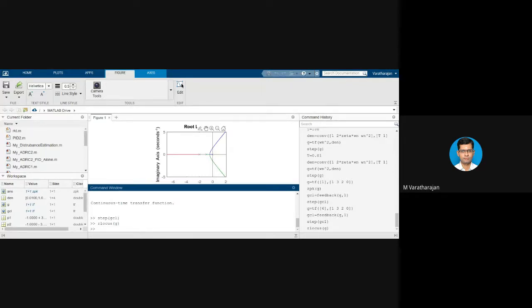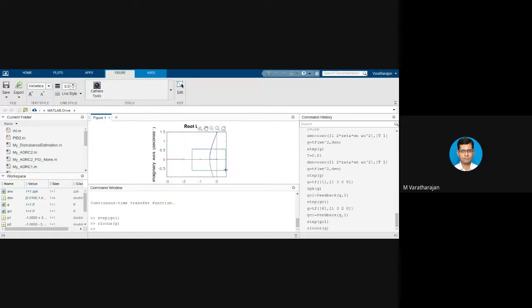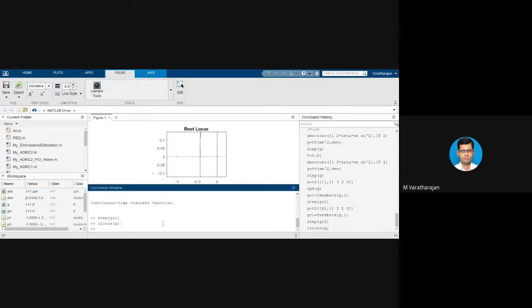Now, what happens is you can infer this behavior, that is, your closed loop pole positions, from the root locus. So what it says is at very low values of k, the X symbol indicates the closed loop pole. They will be on the right hand side. Whatever pole is on the right hand side will move towards the left, and whatever pole at -1 will move towards the right hand side. And what happens? The pole on the right hand side will be more dominant, and because of that, the system will have an over damped kind of behavior.